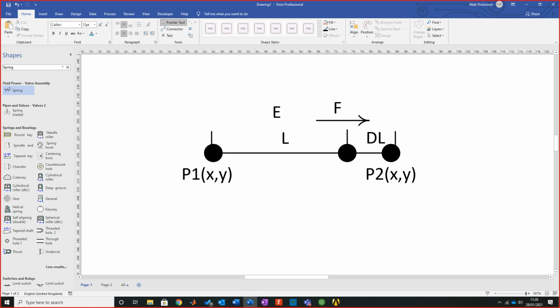You can also physically test what you're getting to actually get your real Young's modulus back. Then what you'll do is map all three against each other. You essentially close the loop, and that is what they call full validation. Verification is what we're going to do here. We're going to calculate out a maximum stress of a truss. We're going to build it in an FEA system, and then we're going to look at what happens.